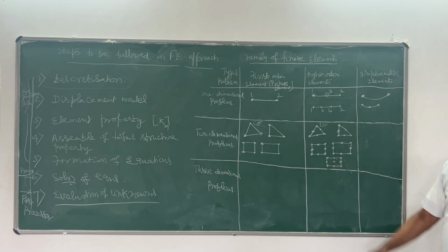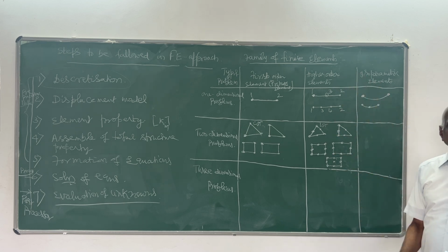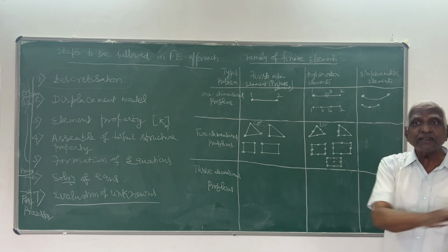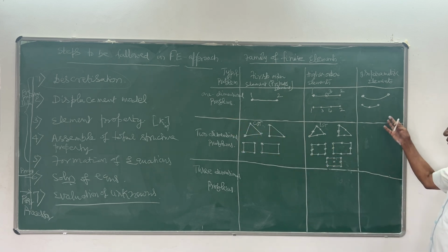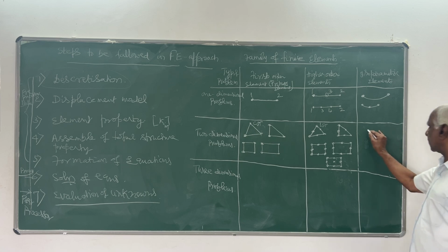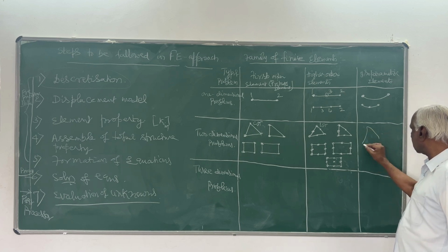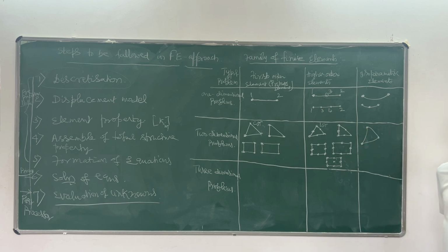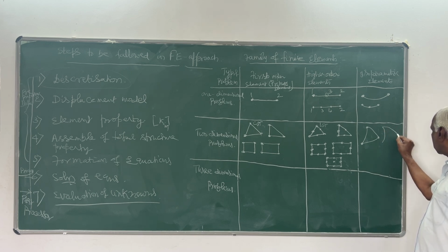They are the higher order elements which we generally use in finite element analysis for discretizing a two-dimensional figure. Then of course, isoparametric: the same parameter used for displacement is used to define geometry, so it will take care of curved boundaries. Like that, basic CST element, or it may be basic LST element.